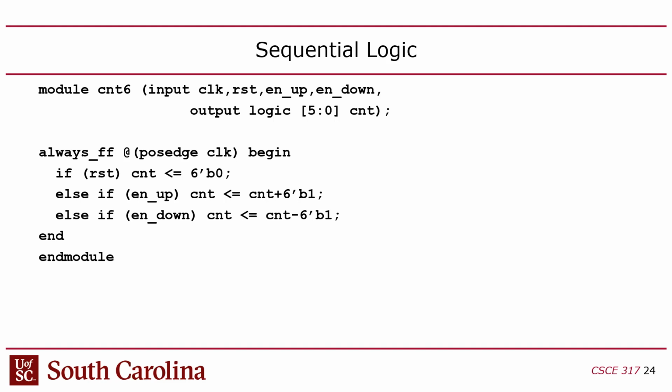So you're going to need to do something very similar to this if you're going to be generating a pulse width modulation, because it'll be based on clock cycles. If you're counting the number of cycles you want the PWM signal to be high, it's going to be based on a count, right? You guys with me? And then, of course, low is a count.